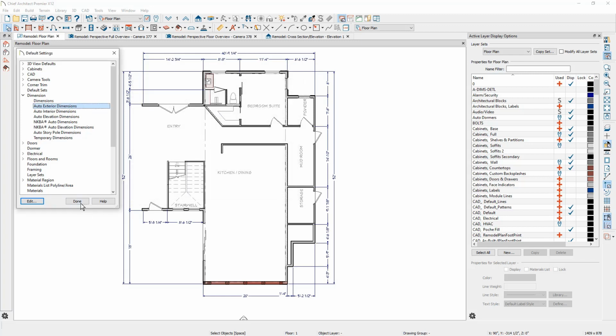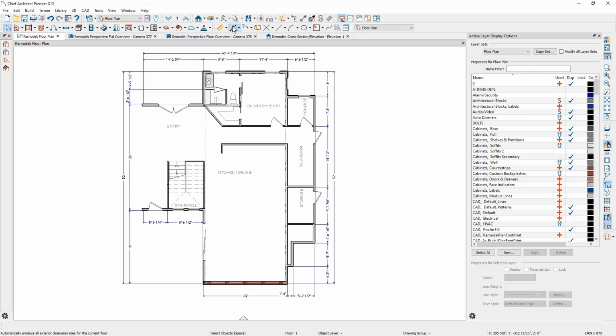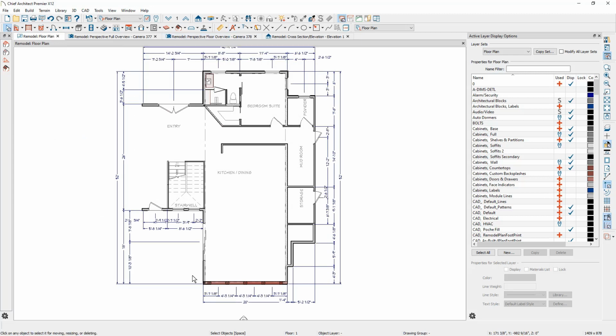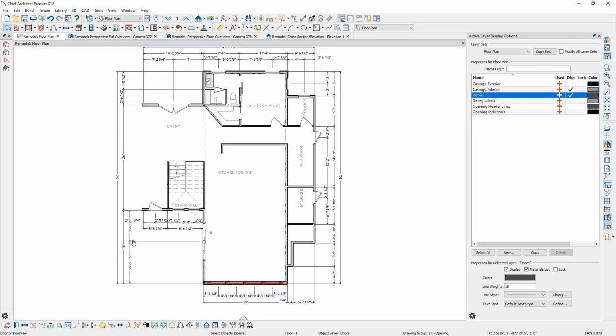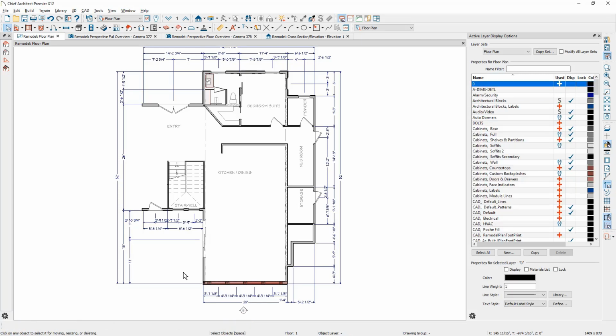control how you'd like to have those openings dimensioned, and then when you run your dimensions, it will then pick up the openings for those objects. And then to make the adjustment, you can simply come over here and type in a value that you want to have that position. Now I've created all of the structural changes that I'm going to make for this remodel